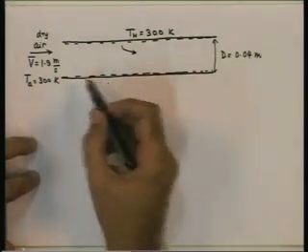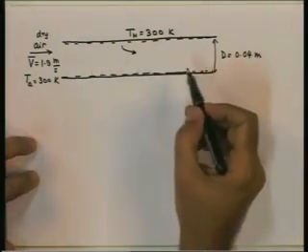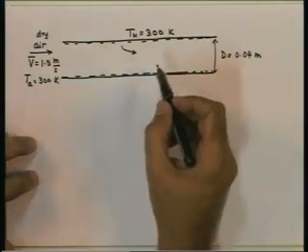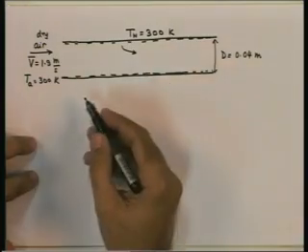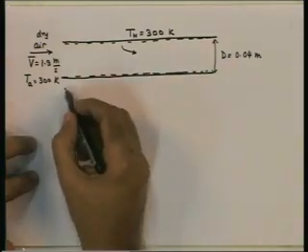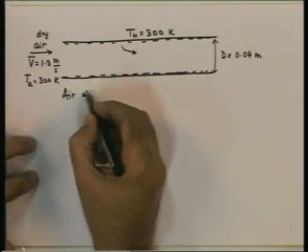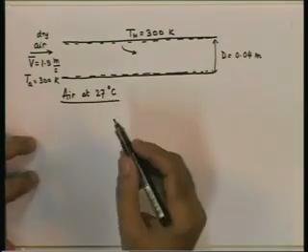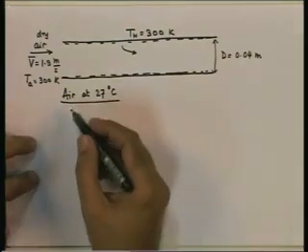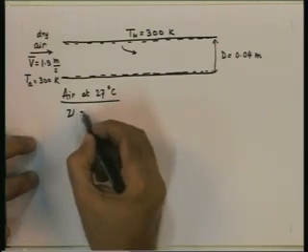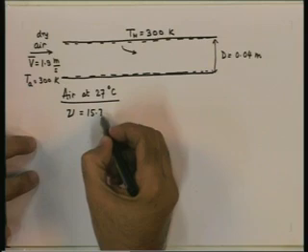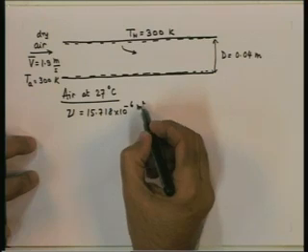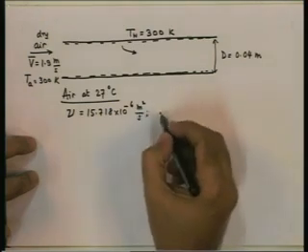Let us assume that the mass transfer is small, so that the properties of air do not really change because of that small ingestion of water vapor. So, we will use properties of air at 300 K, which is at 27 degrees C. Some interpolation will be required in standard tables, but you get nu equal to 15.718 into 10 raised to minus 6 meters square per second.